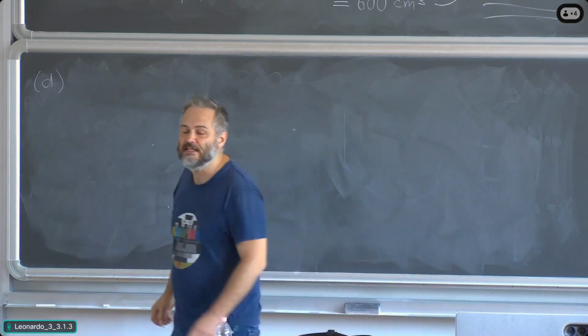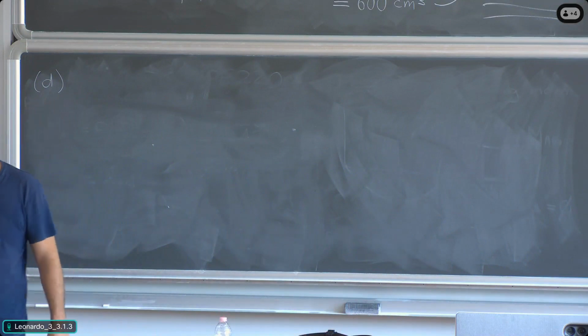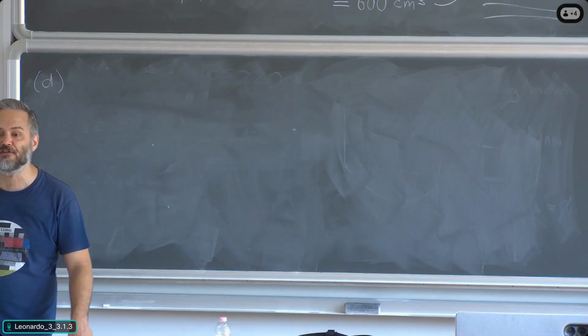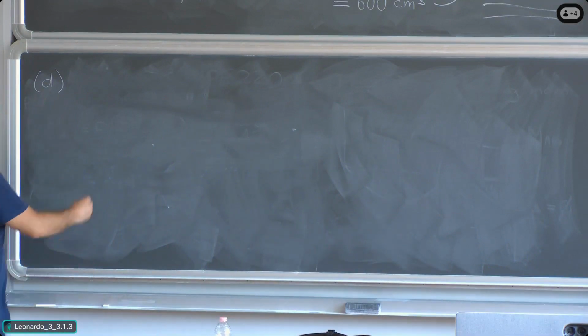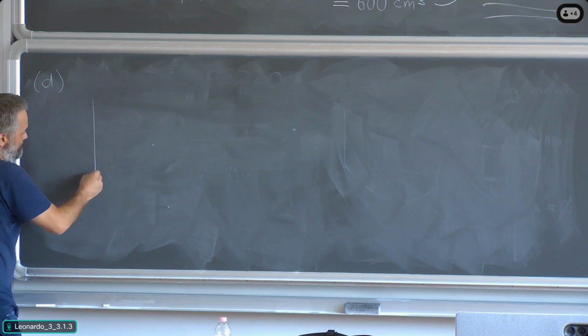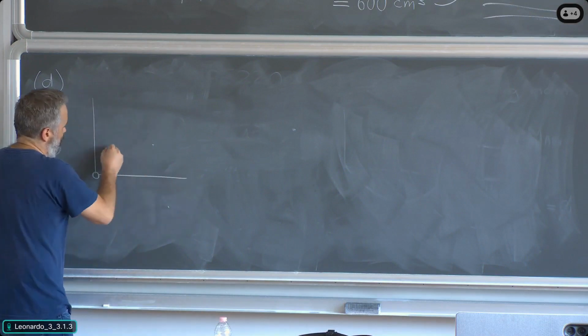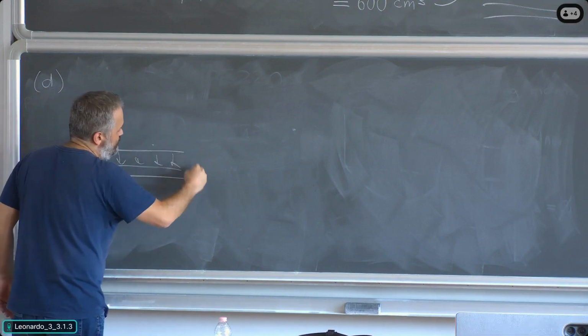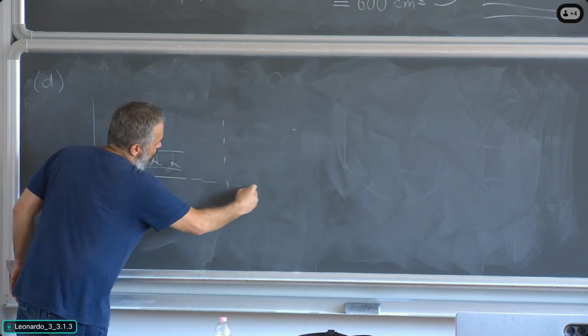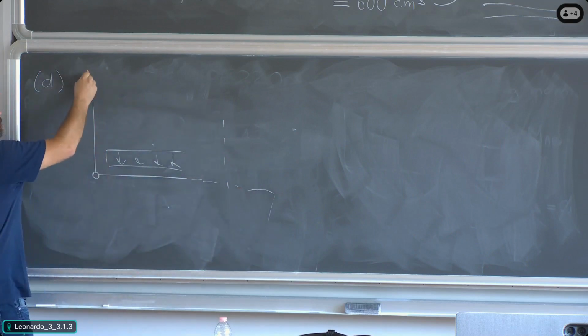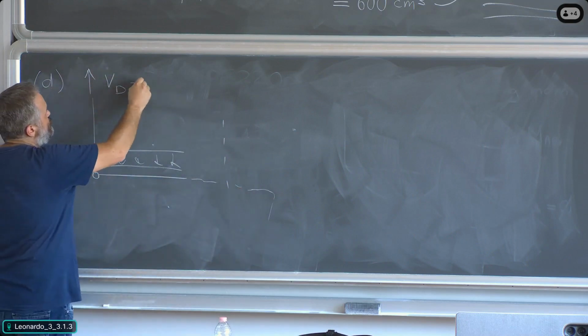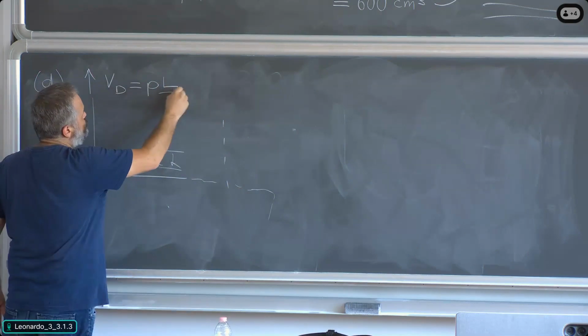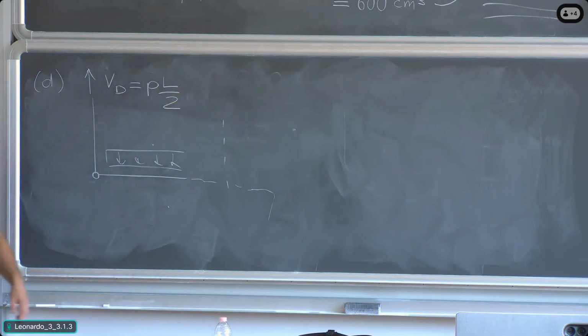Now VD is the reaction force at point D, but it is also the actual force in the tie to the left. So remember, we solved this, there was beam AB with the distributed load, and then the rest of the structure, whatever, okay? I started by working out VD, which is PL divided by 2, which is the force in the tie, okay?